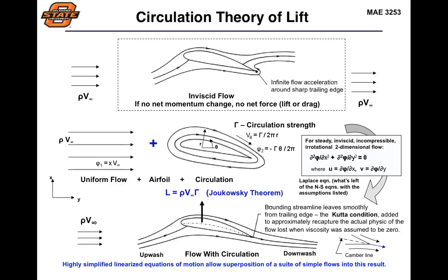So we can put all these things together, and this really becomes the foundation for the circulation theory of lift, where we have this inviscid flow, which is not creating any force. We get neither lift nor drag generated from the airfoil.